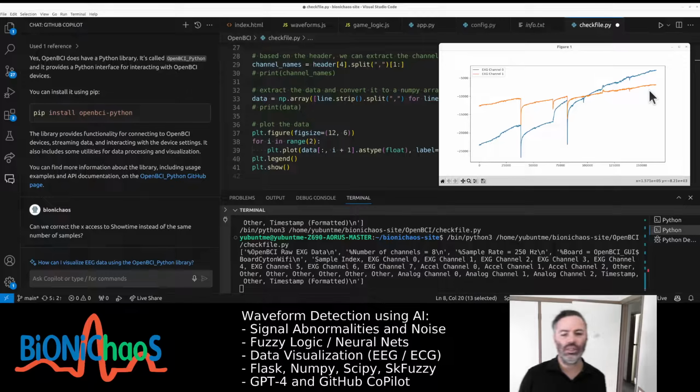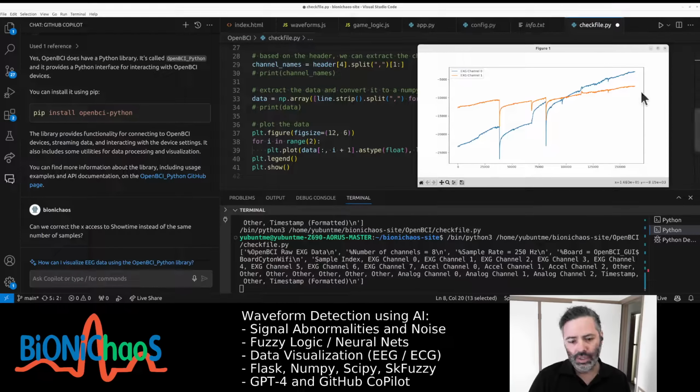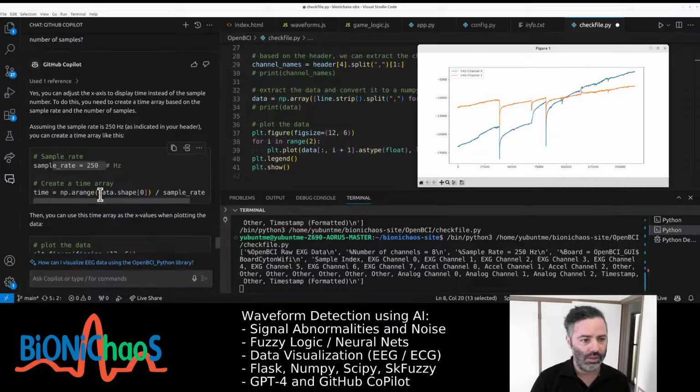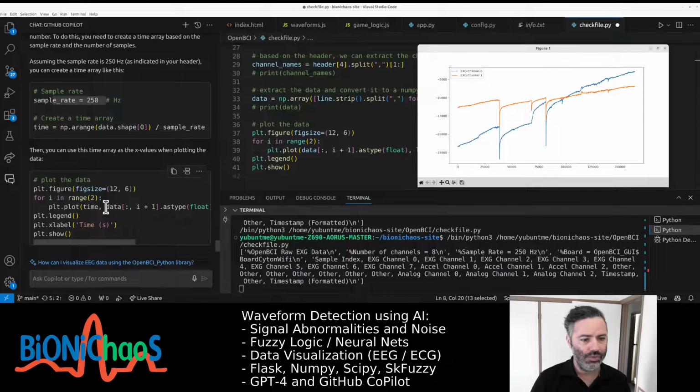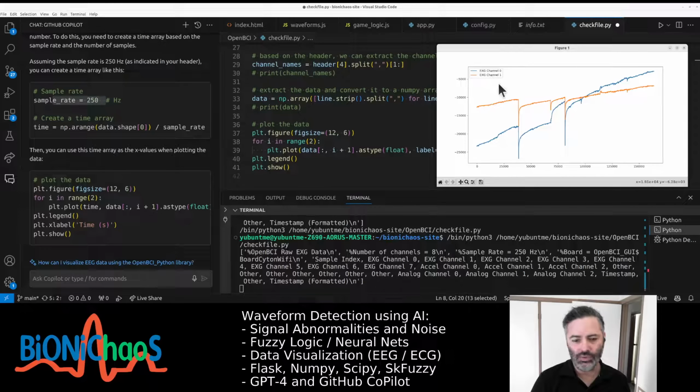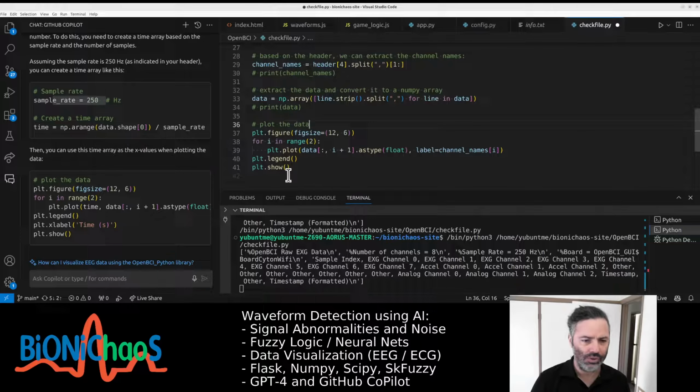So when you record, you need the signal to settle. If you're trying to get your baseline, ideally we need to record for long enough to see what happens after a longer period of time. There's something really wrong if it didn't settle for 10 minutes. There could be a major DC shift, indicating that something is wrong with the recording, as in really wrong. The electrodes might need to be reattached or things like that.